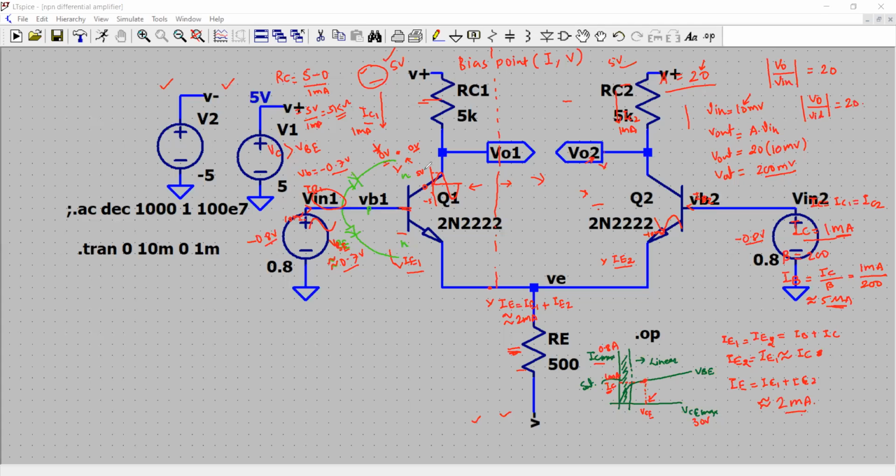Now is this diode forward biased or reverse biased? We have to check once again. So let's clear this out. For example, correct, we'll see that this is my diode, and here is 0 volt, and here is minus 0.8. So P is at negative voltage and N is at 0.